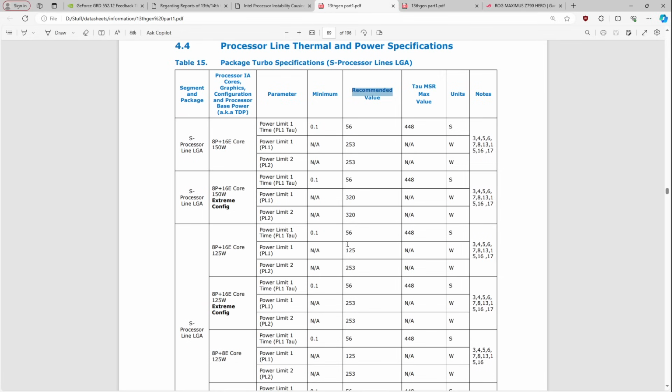I'm not sure how true that is in this scenario, because again, if it's electromigration, then yeah, you would actually prefer it to be thermal throttling at high voltage rather than low voltage. If it's a voltage driven degradation effect, where you just have electrons going through things that they really shouldn't be going through, then you actually want the voltage to be as low as possible.